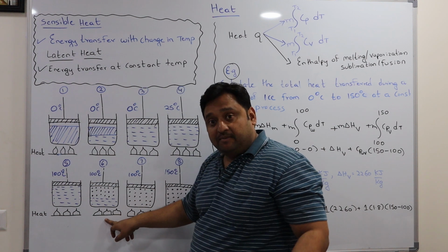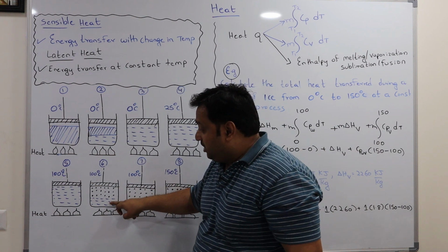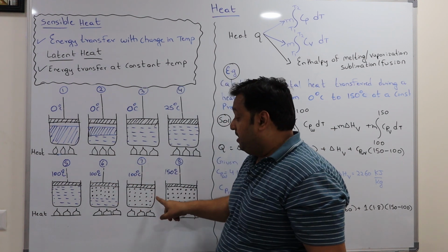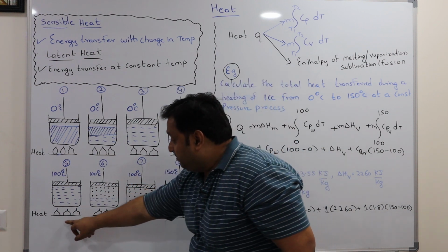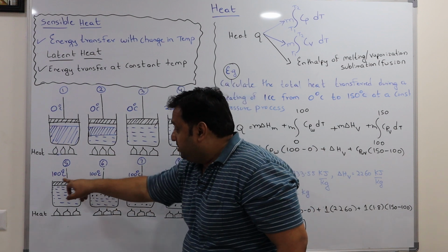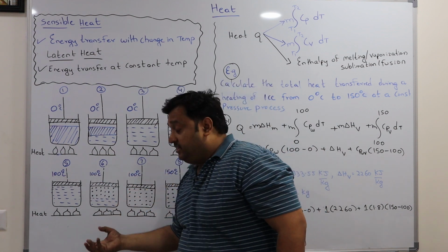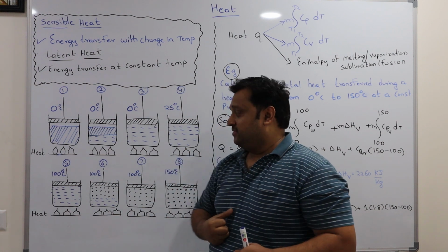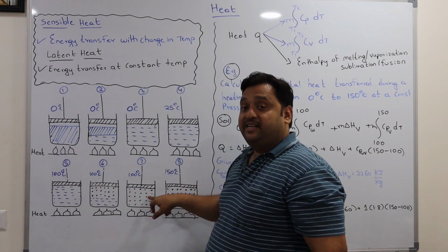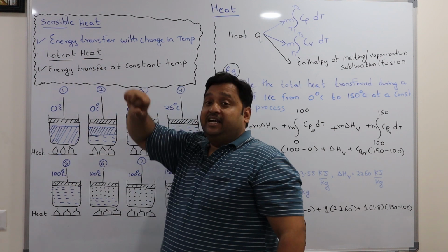If you still supply more heat, the entire liquid will convert to vapor. So during this liquid to vapor change, whatever energy you have supplied, you won't see a change in temperature. Everything comes under the latent heat of evaporation. Again, these three things come under the latent heats.